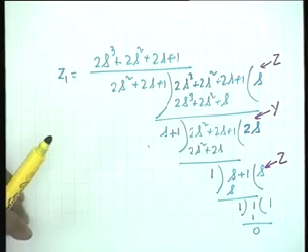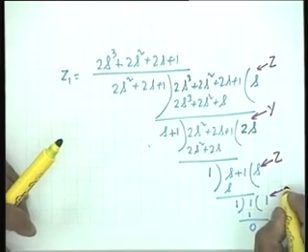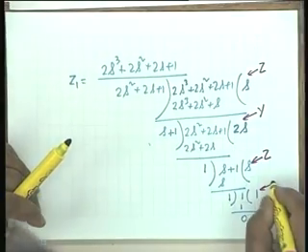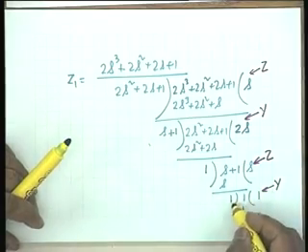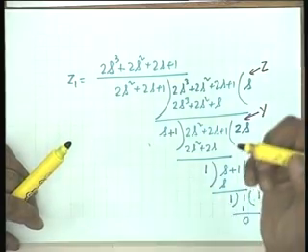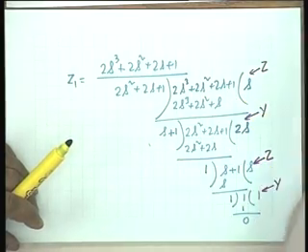The last element is what? Admittance. This is an admittance because you have taken the reciprocal. It just happens that 1 by 1 is 1, and 1 mho admittance is the same as 1 ohm resistance. It may not be so. If the terminating resistance was 2 ohms, then the result here would have been half, not 2.